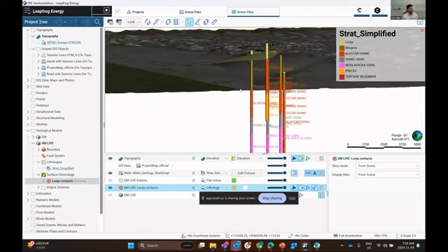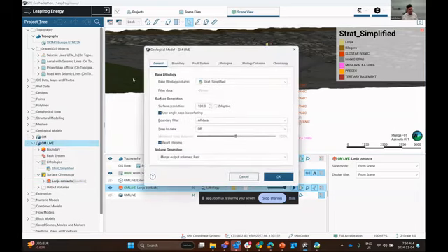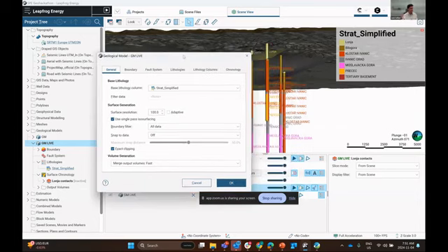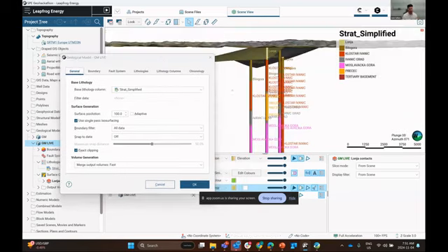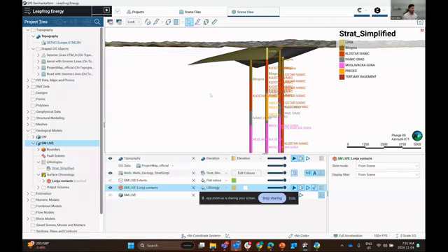And there are multiple different things that you can do to optimize the structure of these surfaces, including double-clicking the geologic model and turning snapping off. We can adjust the boundary filter if we're introducing faults into our model to create offsets. Snap to data basically means that the surface that you build snaps directly to the location of the contact, or some sort of polyline that you draw directly in this 3D scene. So there's multiple different ways that you can optimize how this surface is built.